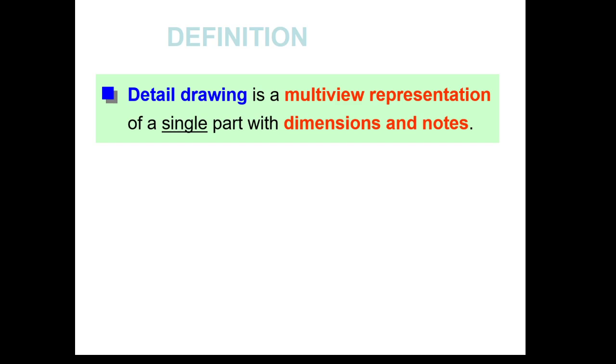To show the projection of the object on a picture plane, the principal side of the object is parallel to the picture plane. You know, for any object we can define 6 principal sides. These are front, back, left, right, top and bottom sides. If the object is complex in shape, it can have a maximum of 6 principal views, a multi-view representation.